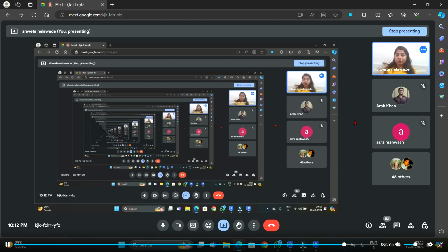Also, when you use grids as a reference, you will need to create them as a different grid type, separate from the actual grids used for construction drawings, because later the reference grid types can be turned off in that particular view. That's how it would be done.